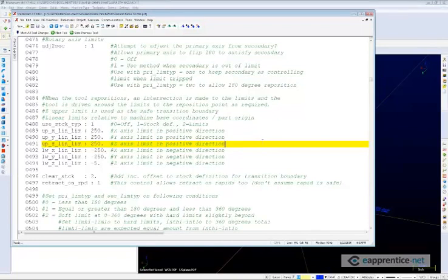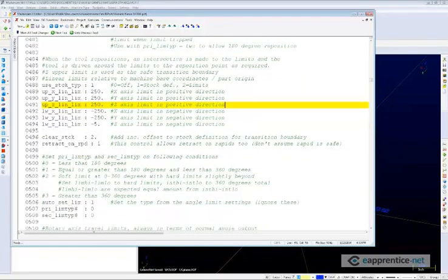The nice thing about the generic Fanuc 5x mil post is that a lot of that heavy lifting is already done for you. So all you really need to know is how to go in and configure the post, and also how to debug where your output is coming from. Because a lot of the math is encrypted, it can sometimes be a little confusing about where you can and can't make edits and what you need to do.